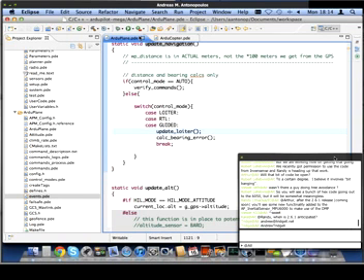But the first thing is just to look for the existing sonar code in ArduPlane, to enable it and understand how it works, and to test it, to make sure that when you have an APM board with a sonar attached, when you raise it above your desk, it accurately measures your altitude in your ground station. It should get your altitude to within a few centimeters.